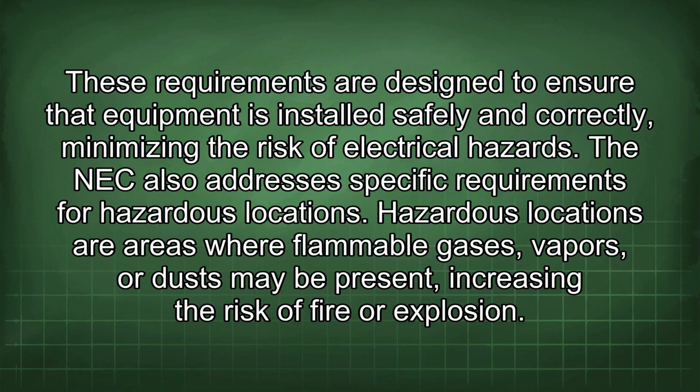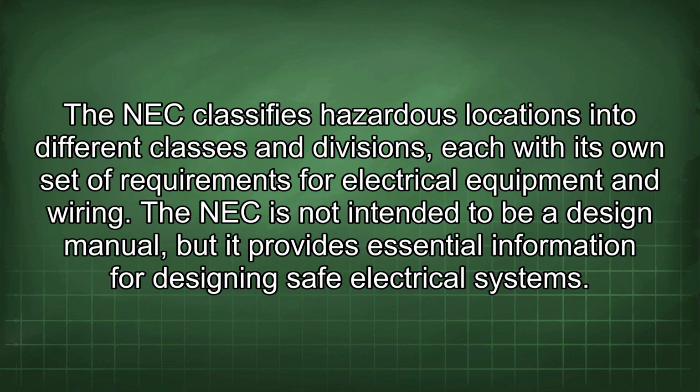The NEC also addresses specific requirements for hazardous locations. Hazardous locations are areas where flammable gases, vapors, or dust may be present, increasing the risk of fire or explosion. The NEC classifies hazardous locations into different classes and divisions, each with its own set of requirements for electrical equipment and wiring.